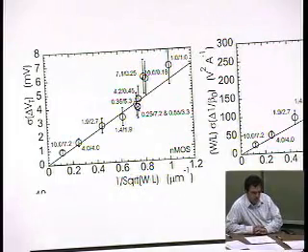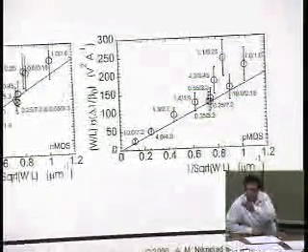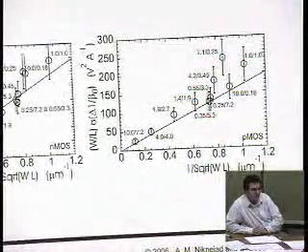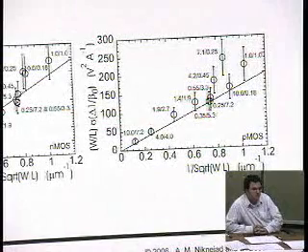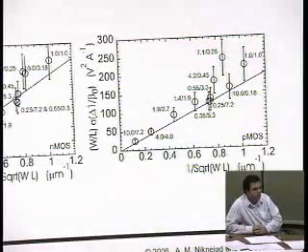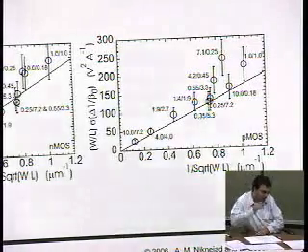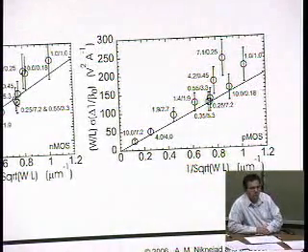That's right. Yeah, with these short channel devices, one issue which was brought up already is that the absolute number of dopants you need is very small. So you're getting into the regime where just 10 more dopants gives you 5 millivolts of offset. And so the absolute number of dopants is not very well controlled. That is definitely an issue for extremely short channel devices. But up into 0.18, 0.13, that's not too much of an issue.